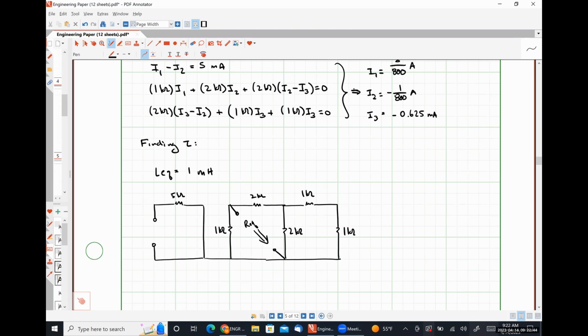So I see 1 kilo ohm in parallel with 3 kilo ohms. So the 1K and the 1K on the right-hand side are in series. So that makes 2 kilo ohms. That is in parallel with a 2 kilo ohm resistor. So 2K in parallel with 2K looks like 1K. That's in series with the 2 kilo ohm resistor in the top middle. So that's why I have 3 kilo ohms on the right-hand side, 1 kilo ohm on the left-hand side. So 1 in parallel with 3, which looks like 3/4 of a kilo ohm.